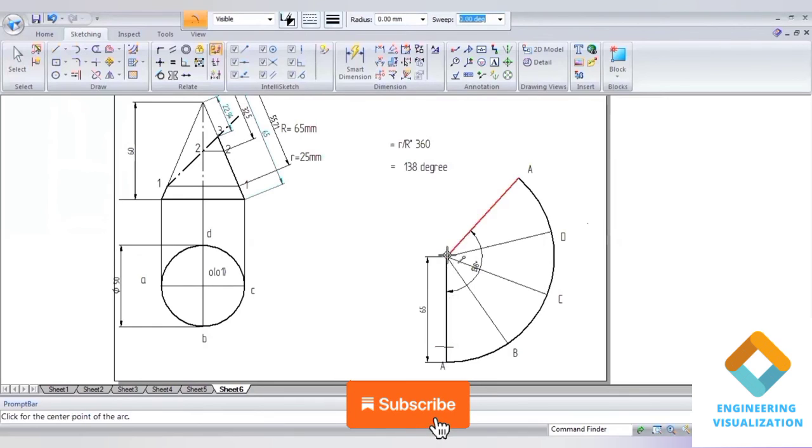The same way you can do it on the vertical edge of A, 55.71, enter. Okay, this is your point 1 here. Now on the vertical edge D we have point number 4. Point number 4 and point number 2 are the same length. I'll consider 32.5. Cut the arc, and the same way you can do it on the vertical edge B here, 32.5. Cut the arc. Now on the vertical edge C you need to cut it for 22.94.